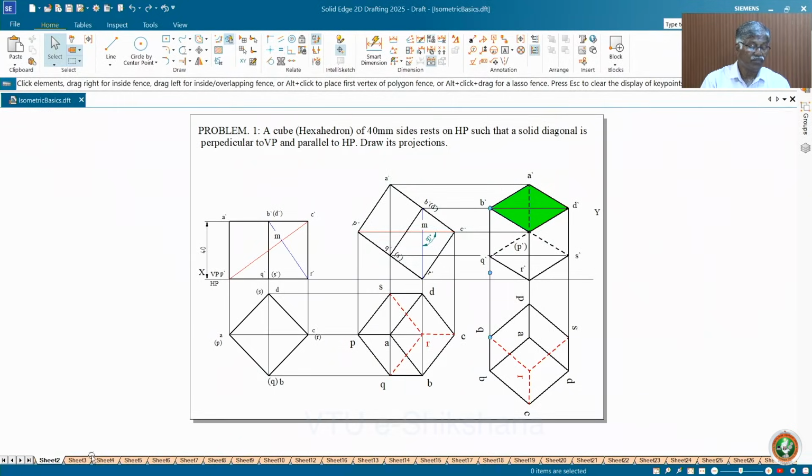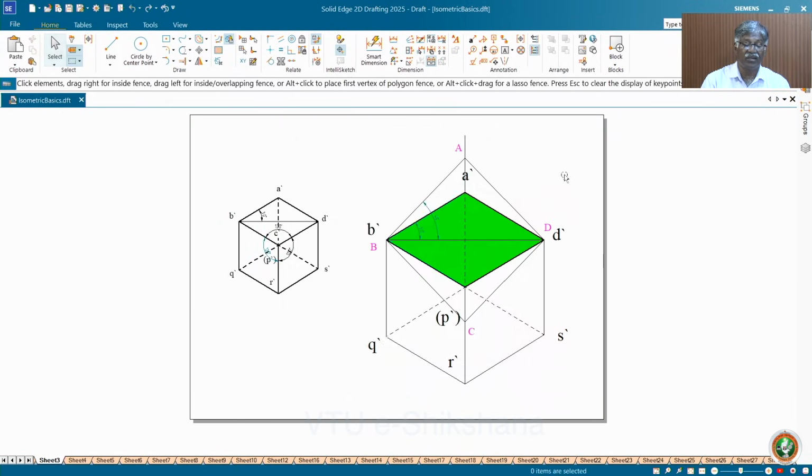Okay. So here it is the case I have taken, the top face, and capital ABCD represents the actual, and the small abcd represents the isometric. Now, let me concentrate on these 2 lines, AB and A dash B dash. This is inclined at 45 degrees if you measure. This is inclined at 30 degrees. So draw 2 lines inclined at 30 degrees and 45 degrees from the same point. This is the actual length, this becomes the isometric length.